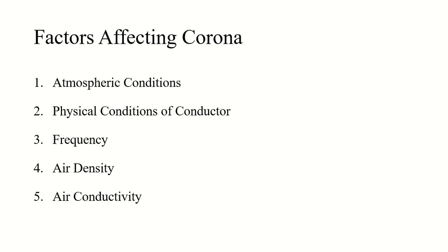Except for that, one factor which I have not mentioned is the line voltage. Remember, earlier when we defined corona, we said it occurs at higher potentials, at higher alternating potentials to be precise. So the greater the line voltage, the greater the chance of occurrence of corona.